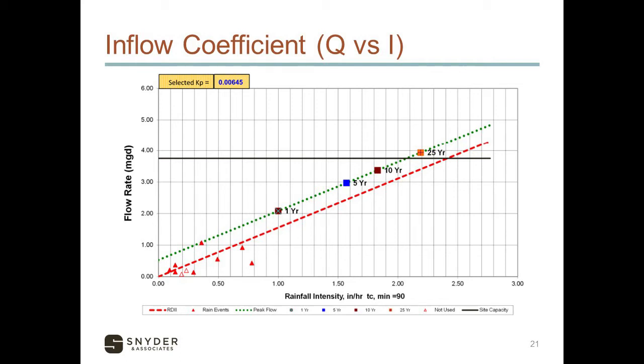Then we're building our infiltration value and our average daily dry weather onto that. And then we're projecting that out to see what our system can actually handle. You can see both have the same slope. So we're using that trend line projection to identify what theoretical storm event can my system handle before it becomes surcharged, or we're going to start having capacity issues.